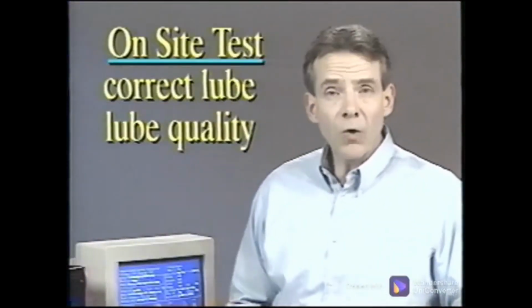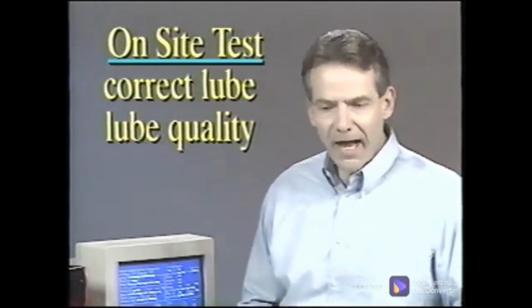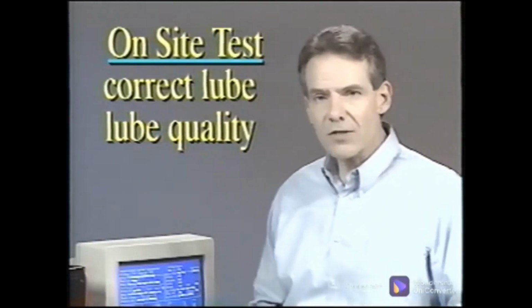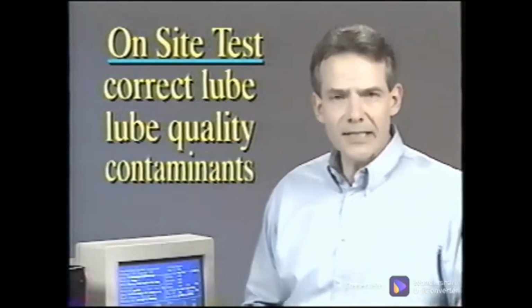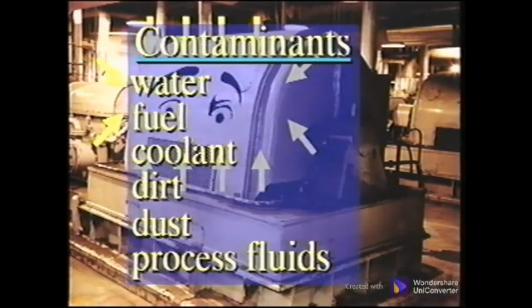We have seen that we can perform on-site tests to verify that a lube is the correct one and to determine any chemical degradation that could lead to a loss of performance. There is another area of concern about the lube that should be analyzed, and that is the presence of any contaminants. Contaminants include any foreign particles from outside the oil system getting into the oil. These include water, fuel, coolant, dirt, dust, process fluids, and other solid or fluid contaminants.